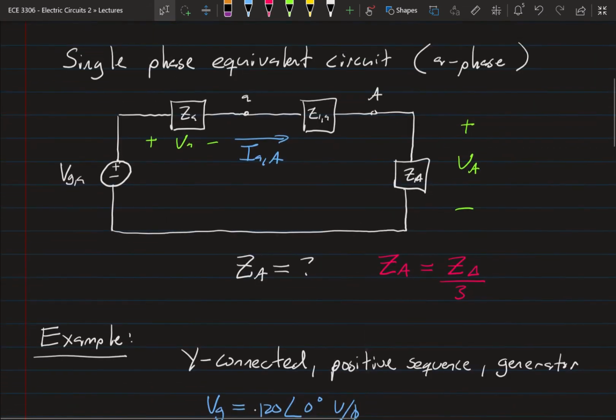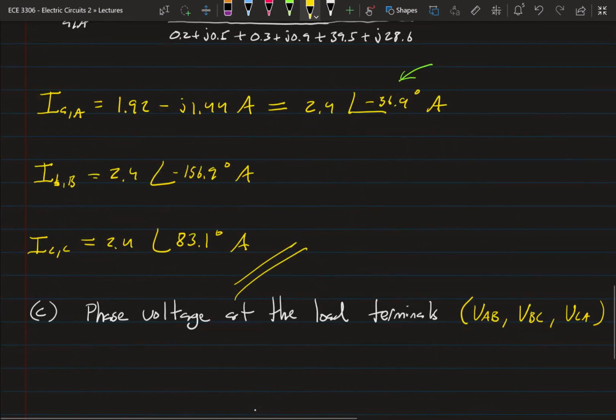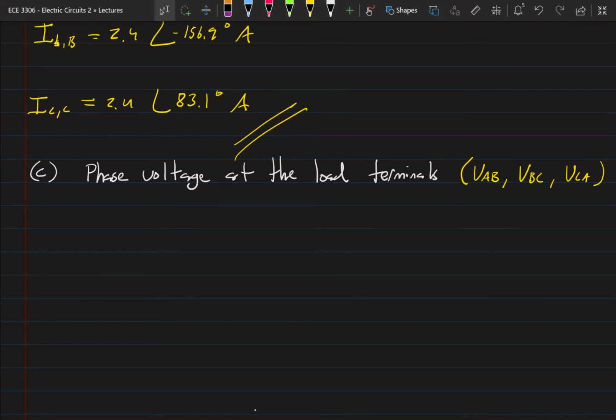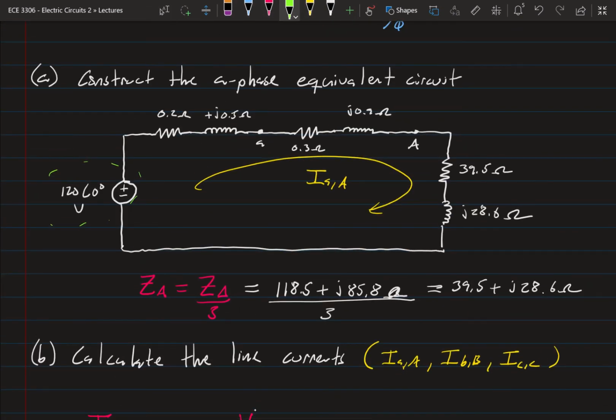Remember, from our diagram at the very top, that's these voltages across each of the delta connected load phases. So the equation for VAB, which we'll use to get the rest of them, is pretty simple, but it's got this thing. You might remember it from the last lecture. It's square root of 3 at an angle of 30 degrees times VA. And remember, VA is just going to be the voltage drop across our load.